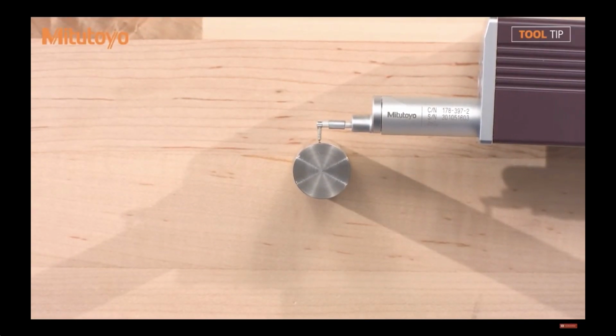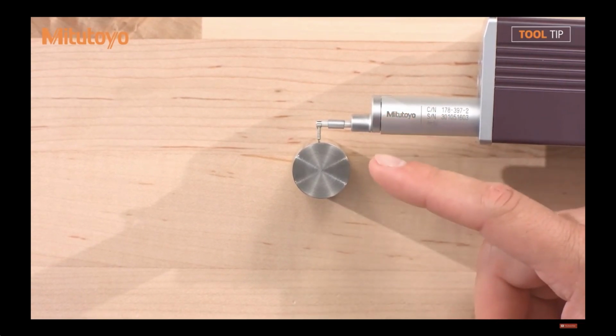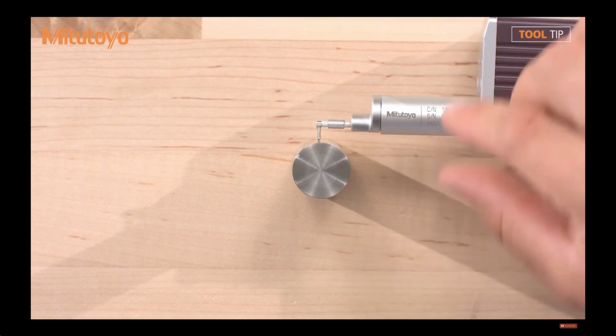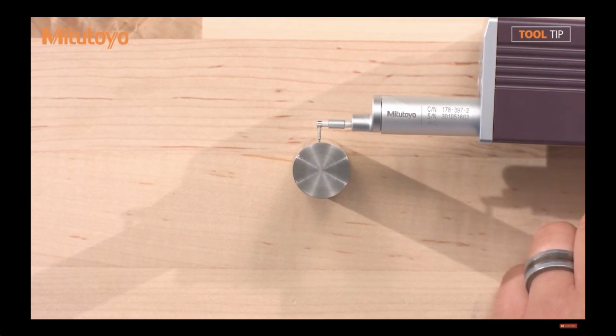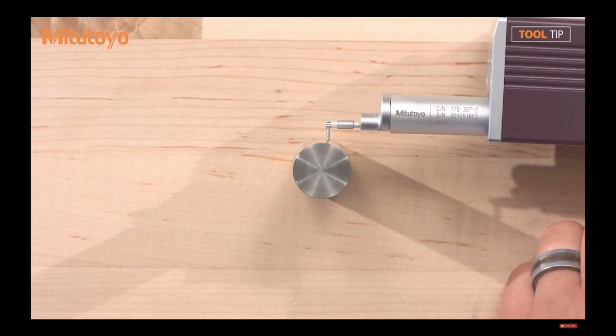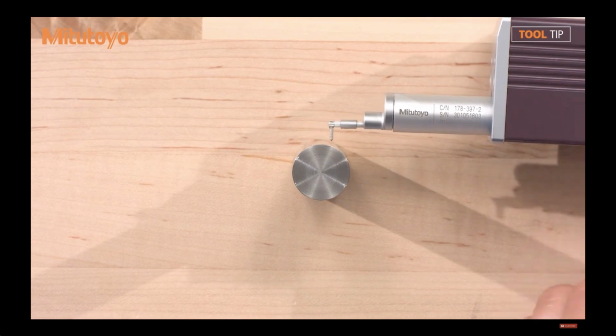So as long as I stay within the stroke of the detector. That's correct. Depending on the unit you have, that will vary how much actual stylus travel. So as long as I stay within my stylus travel, I can measure radially across the part. That's correct. That would be no issue to actually have the stylus traverse from side to side. Obviously, I'm moving the whole drive unit here, but in an actual measurement process, it would just be the detector moving the stylus. Drew, that makes sense, measuring round parts versus straight parts.